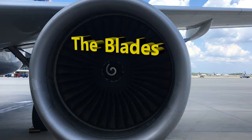In other words, it's going to be 180 degrees from each other. And again, please pay attention to markings. You can't just arbitrarily pick fan blades and stick them somewhere or force them in, because that's wrong. You have to be very deliberate with the installation of the specific blades. So again, pay attention to markings, and of course, follow the aircraft maintenance manual regarding the installation of all of that.